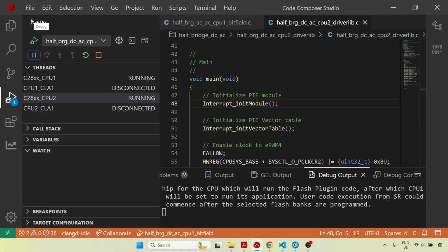We had considered various topologies of the half bridge module. That is, we had seen the half bridge module being used as a bidirectional buck converter, as a bidirectional buck boost converter, and now as a DC to AC converter. This shows the flexibility of this particular half bridge module. With this, I'm going to conclude this section in the next lecture, and in the next section we will examine the full bridge converter, which consists of two half bridge modules connected together.